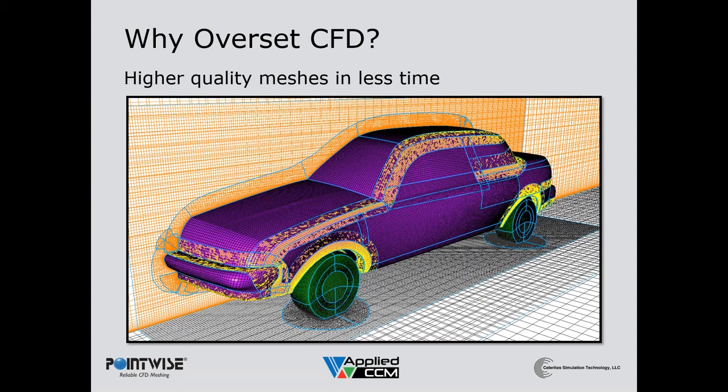Despite the overwhelming movement of the industry towards unstructured meshing and unstructured solvers, there still seems to be, at least from my viewpoint, a lot of people who still want to use structured meshes, for a variety of reasons: accuracy, simulation time, all this kind of stuff. But for industrial scale problems, they're just too time consuming to make, even for experienced users. So Overset really reduces that burden, because like Ralph talked about, you make these meshes on a component level or on a portion of the component level, and the Overset grid assembly process is really what takes care of the connectivity between the component grids themselves.